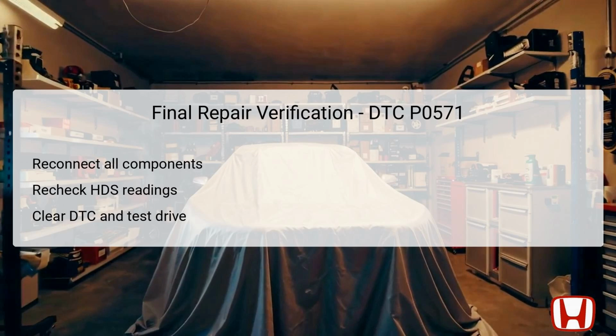After verifying the readings are normal, proceed to clear any stored diagnostic trouble codes from the PCM. Finally, conduct a test drive to ensure that the brake system operates as intended without returning the DTC. This step confirms the vehicle's readiness for daily use and ensures that all systems have returned to normal functionality.